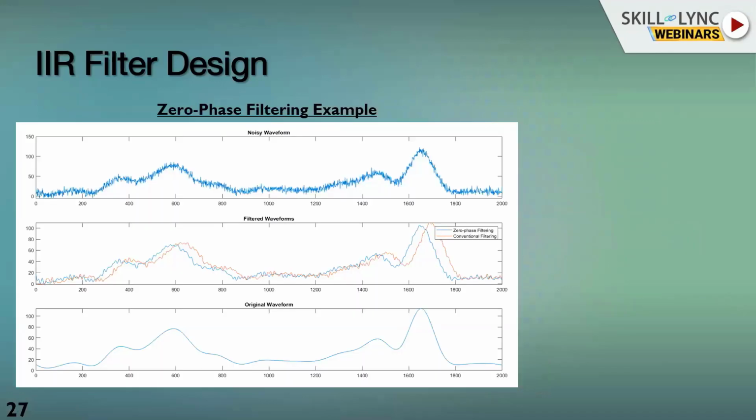Then we have zero phase filtering, which is a very important technique in applications where real-time constraints are not present. Like audio signal post-processing or speech signal post-processing, where we have the complete signal available to us before the processing. It's not like the signal is coming in real time and then we have to process it. So we have the complete song or noisy speech signal, and we have to denoise or filter it for some noise cancellation or something.